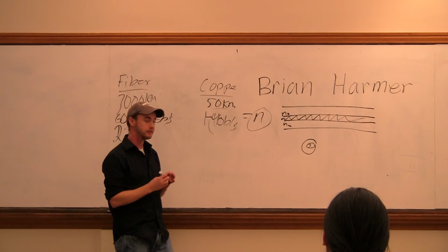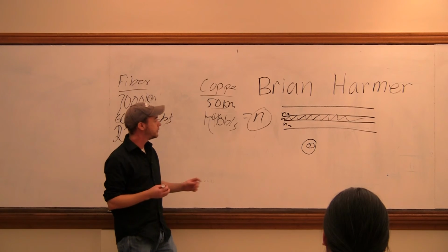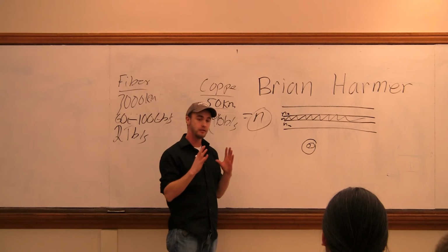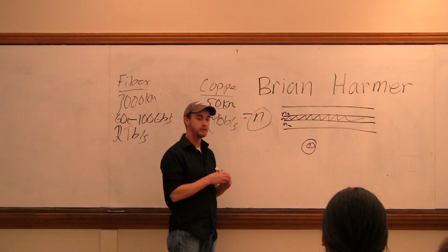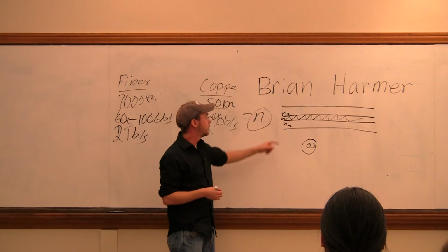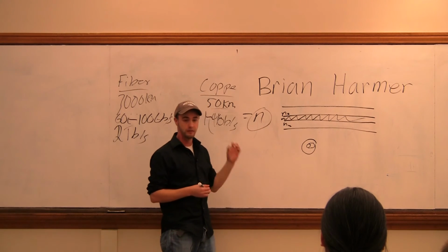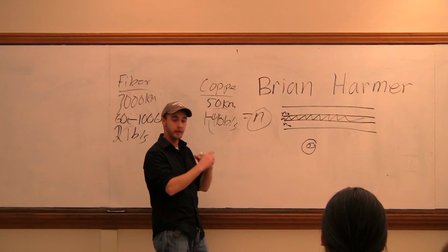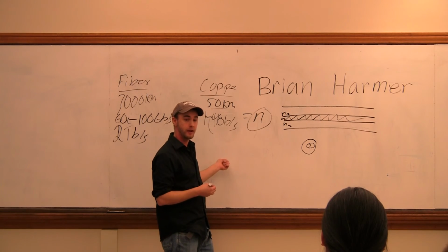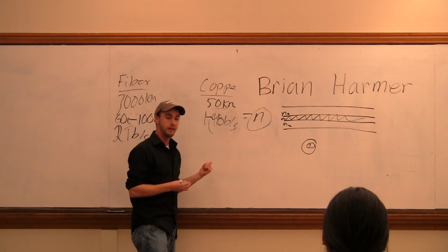For single mode fibers, you only have to deal with this kind of step. Whereas if you want a whole bunch of different modes through that fiber, you actually have to have a gradient in the cladding, or in the core itself. So different modes will propagate properly, because each wavelength will be affected by your index of refraction in a different way. Does that answer your question?